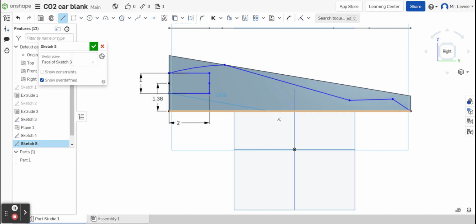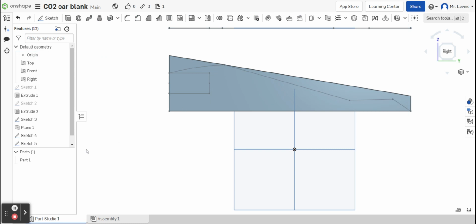Therefore, it's a shape. So make it a shape. So if you think something's not extruding or something's not working, you might have to trace back over it a couple times. Just make sure you're in sketch 5. So sketch 5 is going to be the side view. Sketch 4 is the top view. So let me pop this into the corner, just so I can see an isometric view.